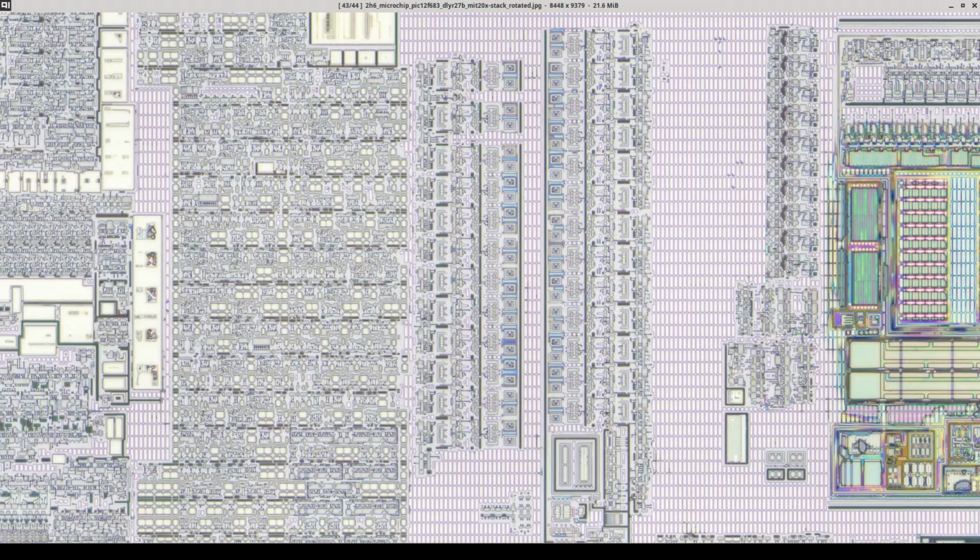as separate memory. It's far more common to have either a boot ROM or user software running out of flash will read configuration for the oscillators, your watchdog timers, your brown-out detector, and whatever. And the first couple of instructions the CPU runs after boot will then take those settings and write them to latches of some sort that actually control the relevant circuitry.